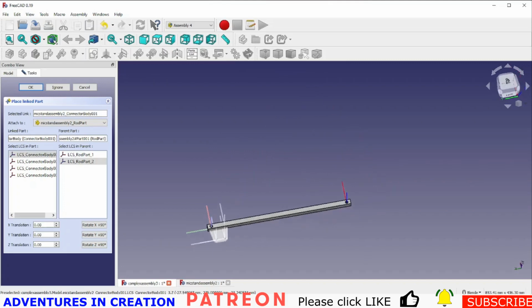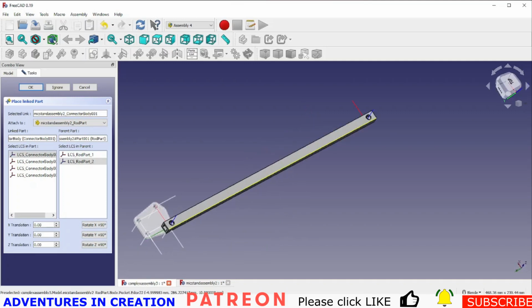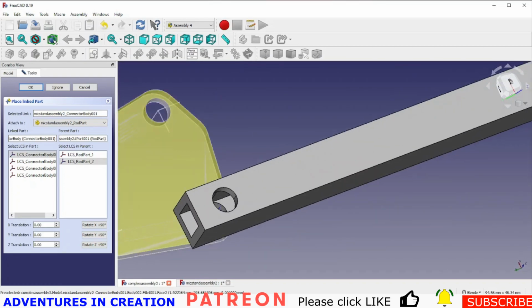If I put it on that end, I probably want to rotate it. I'm going to rotate it around my Z by 90, and then I'm going to rotate it around my Y. No, I didn't want to rotate around my Y, it was X. There we go. So that's the rotation I wanted. It was actually the X that I should have used. And that has it now aligned the way I want it aligned.